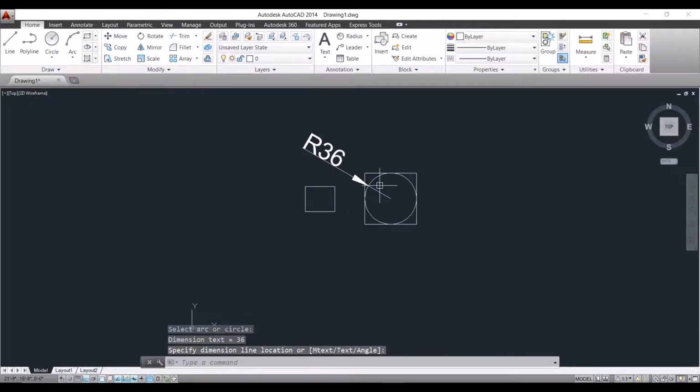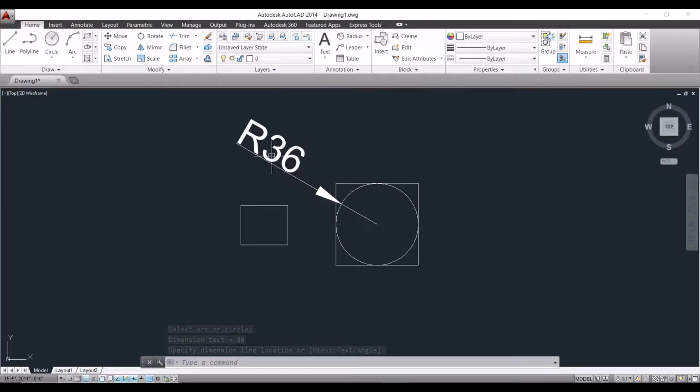Okay, this is the use of scale command. Okay, there are three things. One is just directly scaling with the scale factor, 1 times, 0.5 times, 0.3 times, 10 times, 100 times, whatever you want to scale into X factor, you can do that. The same with copy command also you can do that. Okay, and then the other thing is clicking a reference and giving an exact value. Another option, clicking the reference by giving the exact point to point distance by specifying reference, and followed by specifying the points where we don't know the exact dimension.